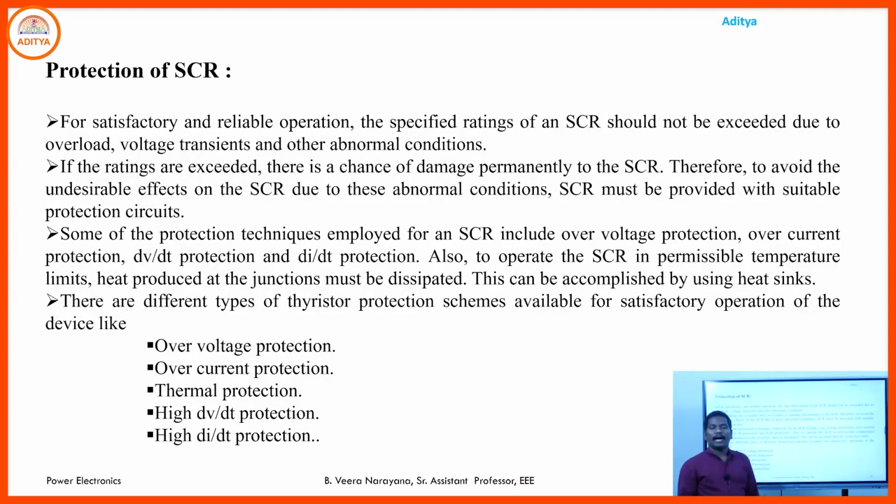We already said all the power semiconductor devices have low thermal handling capability. That means even for a small period of time, if the voltage across the SCR and current flow through the SCR crossovers its rated values, then those devices may go to the damage. So for safe and reliable operation of the SCR, you must ensure that the current flow through the SCR and voltage across the SCR cannot exceed the rated value. So always the operating values must be below the rated values for safe and reliable operation of the SCR.